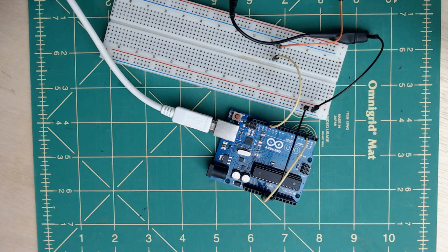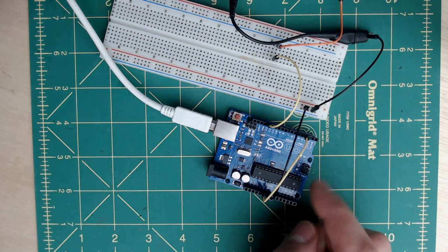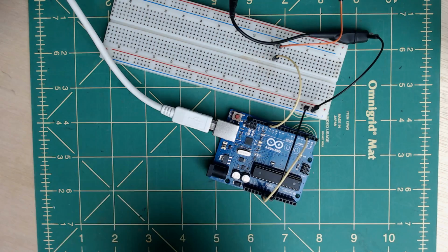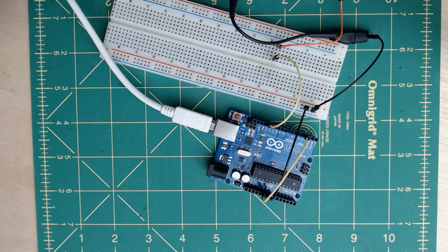Now, when you're using an input, these are high impedance inputs, and when you declare an input, it's basically what's called floating. So what you need to do is use a pull-up or pull-down resistor, or connect the pin to a device that drives the pin low or high. You don't want to just leave a pin floating, as you'll get erroneous inputs. And then you'll sit there and bang your head against the wall and wonder why your code isn't working.